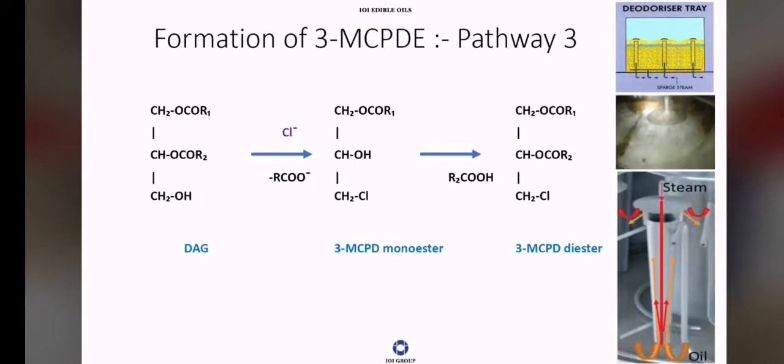Now, what this does in effect is it creates a circulation within the tray to allow large surface area contact and proper stripping of the impurities in the oil. The lowest picture shows the steam lift pump, sometimes also called the mammoth pump, and how it works. You have oil being drawn in because of the steam's upward movement.